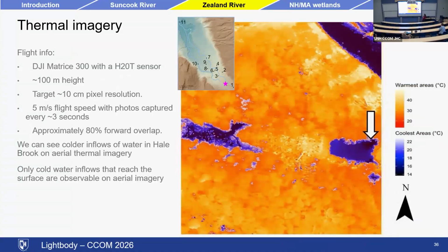In addition, when we're looking at streams, another very important aspect is temperature. And so when we're looking at groundwater inflows, we can actually pick that up with thermal imagery. The black here is showing very cold water that's flowing into a puddle here. This is sort of in the diversion site. You can see that our stream water is pretty cold. And when it's flowing through the ground and then coming out into a warm puddle that's in the sun, we can see that groundwater coming in.